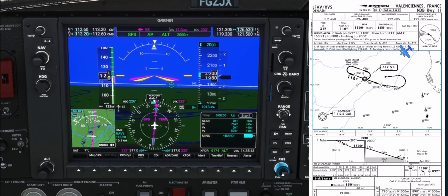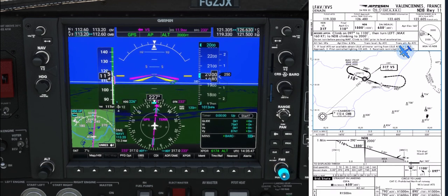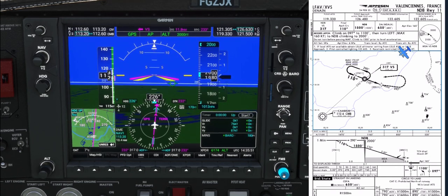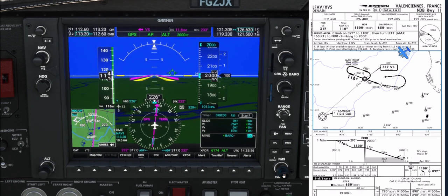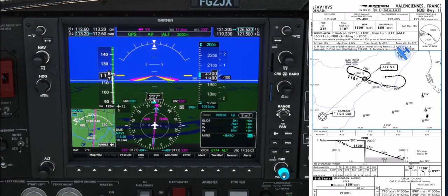Now that we are approaching Victor Sierra, we quit the GPS navigation to switch to pure NDB navigation. We will not use the radial 046 degrees of Combray to cross-check the position of the NDB, just working with the NDB to make things a bit more difficult. So we can put bearing 1 and bearing 2 on ADF, set the minimums at 650 feet, set the CDI on the holding radial to help for positioning.